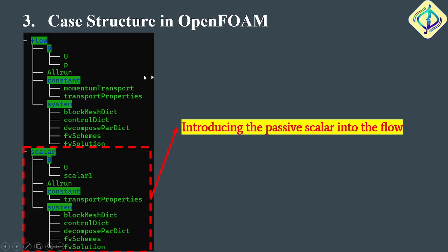Okay, so once you have run up to 50 seconds, that last time step velocity, we will copy it into the scalar, because at time step 50 you will have the flow completely developed, and that parameter is what we require to initialize the scalar part. Okay, so I'll show you how to do that. And again, scalar will be the thing that we will be modeling into our solver. So again, this is a parameter that we have created.